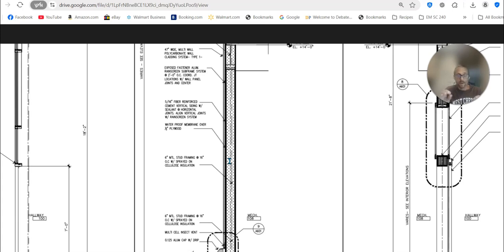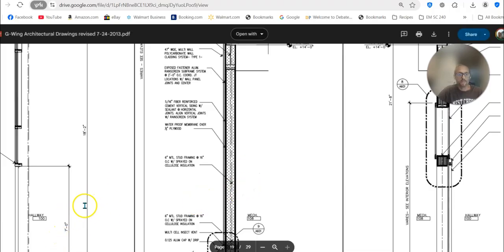Those are two very different R values because metal has almost no insulating properties, whereas spray foam has very high insulating properties. So you just have to keep in mind that even though it looks like there's one cross section, there's actually two cross sections: one with the metal stud in the middle and one with spray foam in the middle. Okay. All right. So hopefully that helps you navigate the construction drawing for purposes of a heat load calculation.